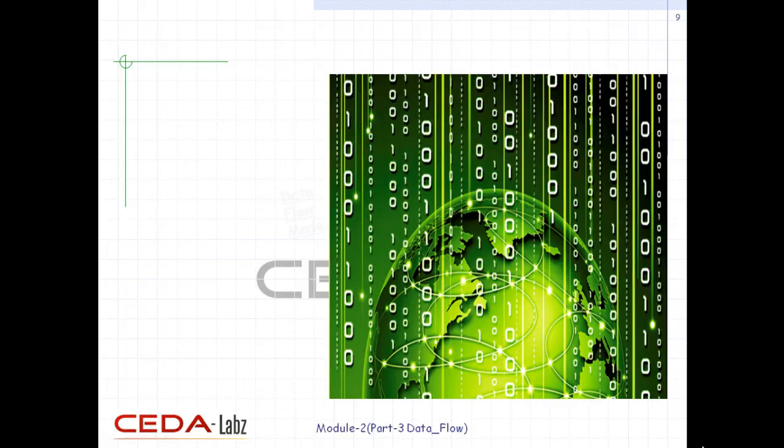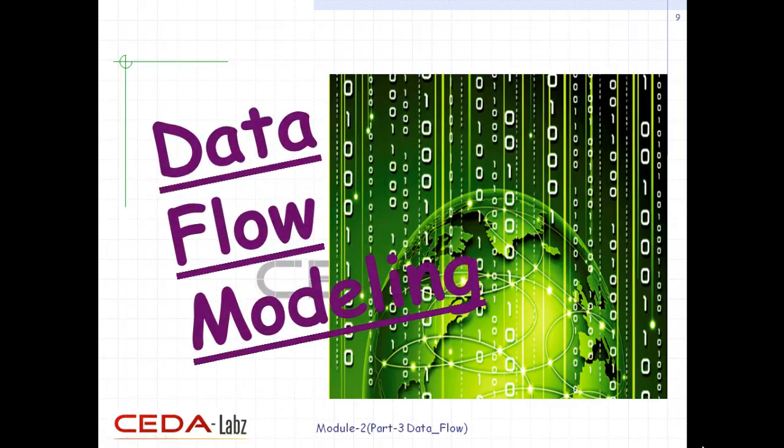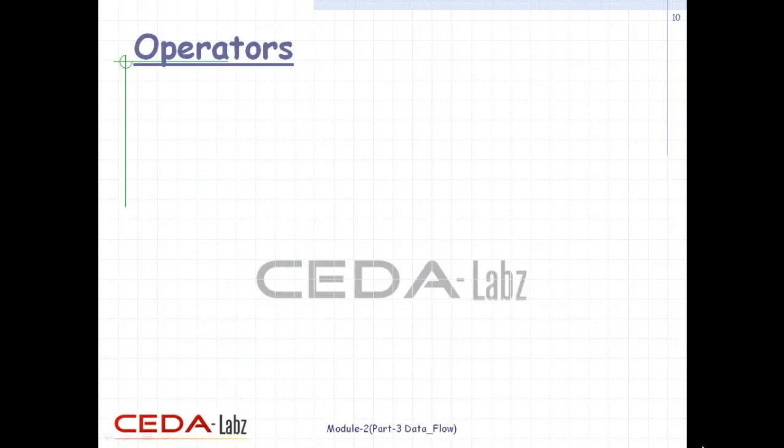Data flow modeling provides a powerful way to implement a design. Verilog allows a circuit to be designed in terms of the data flow between registers and how a design processes data rather than instantiation of individual gates. Later in this tutorial, the benefits of data flow modeling will become more apparent.